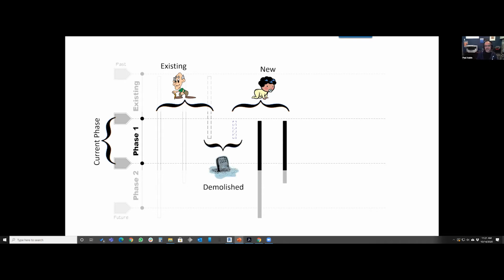But this stuff here in the middle has been demolished, so instead of showing as either gray or solid black, they show in those dashed lines. And then, of course, this one is using a crosshatch and a blue color because it's both created and demolished in the same phase, so it's temporary. So those are the 4 different conditions that can be applied to things.